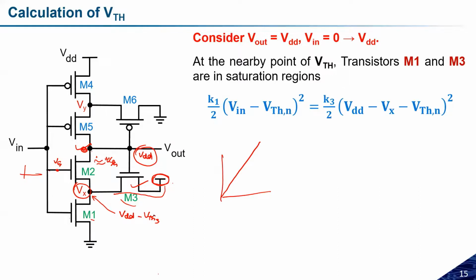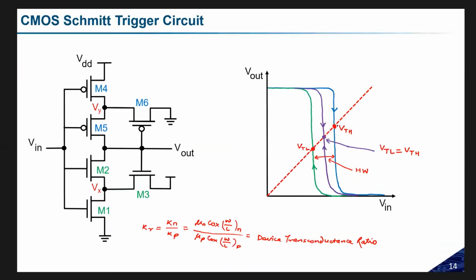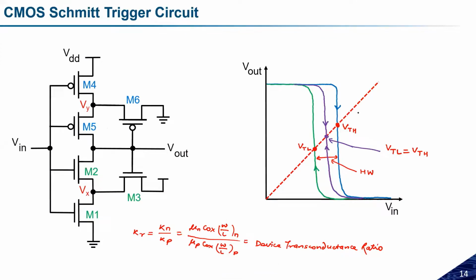So this is the VS of this transistor M2, and VG is even less than the VDD. So if you see, this will not be in the active region, right? It is not up to the VDD; it has started transitioning. If you go back to the previous slide, at this point this input is not completely VDD, and at this point it is even less than VDD, close to the mid value.